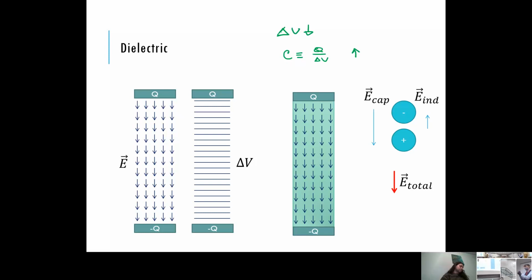They put a little crosshatch on the top and it will bow outwards when you blow a capacitor. And the reason they do that is so that when you open up the machinery, you can see which capacitor failed, and so you can pull it out and drop a new one in. They purposely introduce a weakness so that you see it.